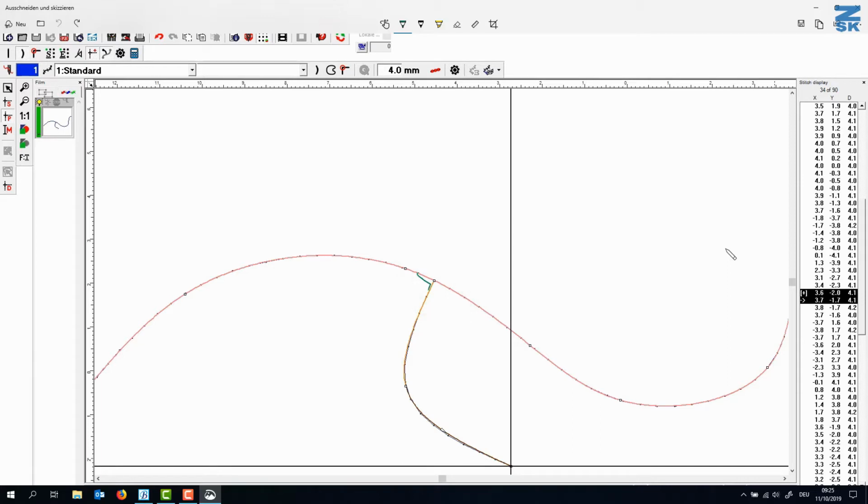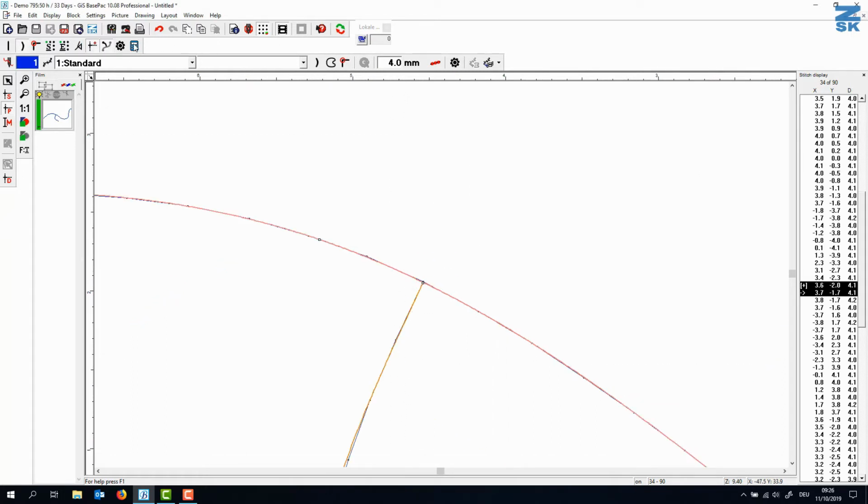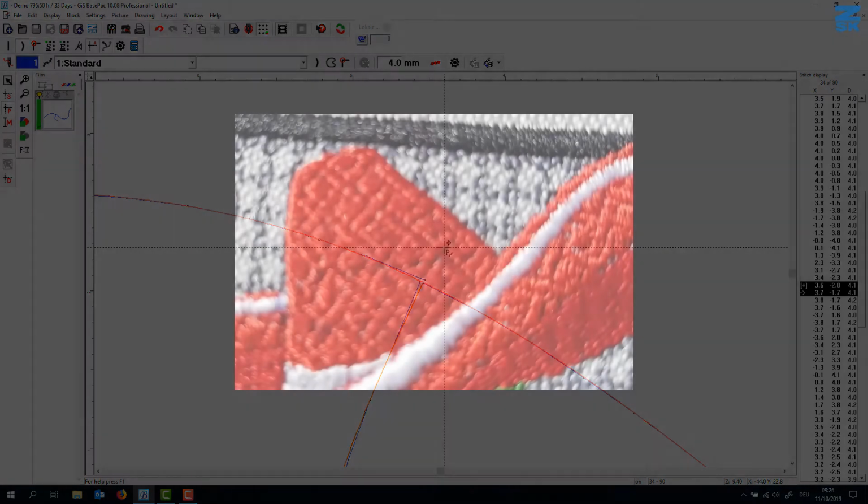You will see something like this because all of a sudden the frame changes direction. What we do, we actually program this stitch slightly off, which then evens out this pulling towards this side. Therefore, we have here our overhang. So let's say I add another 0.2 millimeters. You see now this one actually stands out and it will even out the pulling on the machine.